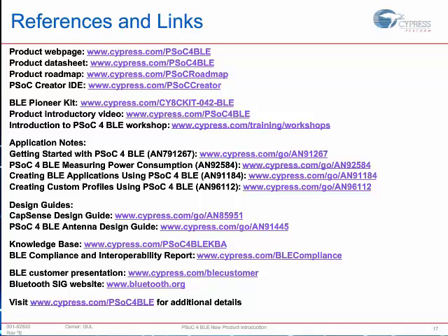I think you answered this when you were talking about the BLE stack, but is the ARM core shared, essentially used to run the BLE stack, or is there an independent core for the BLE support? This ARM core is a single ARM core. It is shared with all of the peripherals and the BLE stack. It does the management and the time sharing between the Bluetooth part of the system and the rest of the peripherals. But the CPU, which is the ARM core, and the flash, up to 256K available, are shared for your application and your Bluetooth low energy aspect of the system.